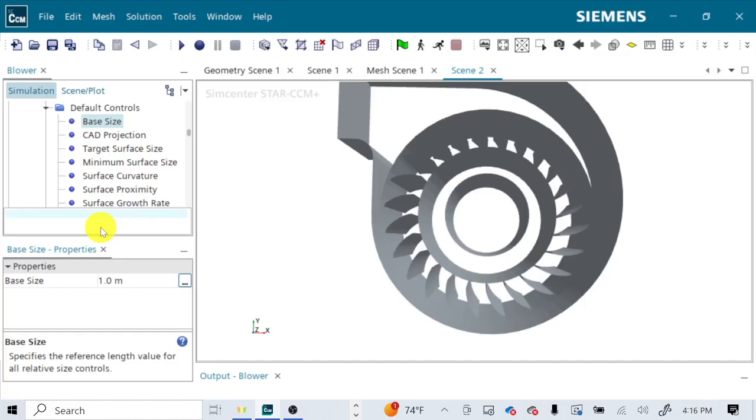Well, how big is this thing approximately? Oh, it's 0.3, right? 0.3 meters? It's 0.3 meters in Z, but Z doesn't matter for mesh. We only care about X and Y. A little tricky though. It looks like it's also about 0.3.